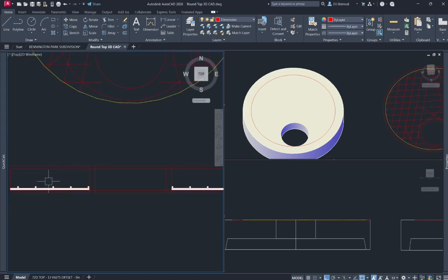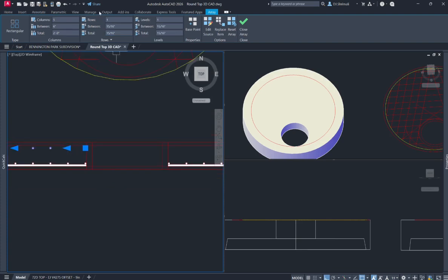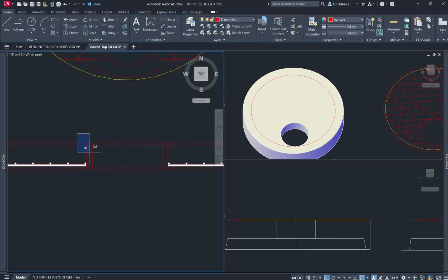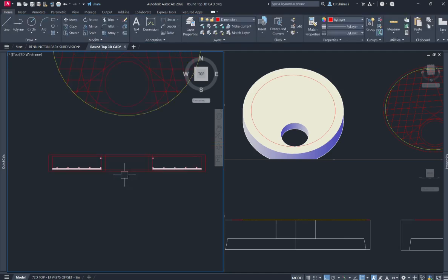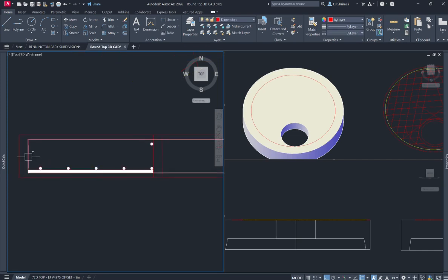Okay, and from the side it has to be 2 inches, and on the sides it's going to be the circumferential wires. At the top, since the diagonal rebars need to be at the bottom and at the top to reinforce the opening, I'm creating 2 rebars on top as well for those diagonal rebars. So that band bar and diagonal knee bar need to be at the bottom and at the top at 1 inch cover.